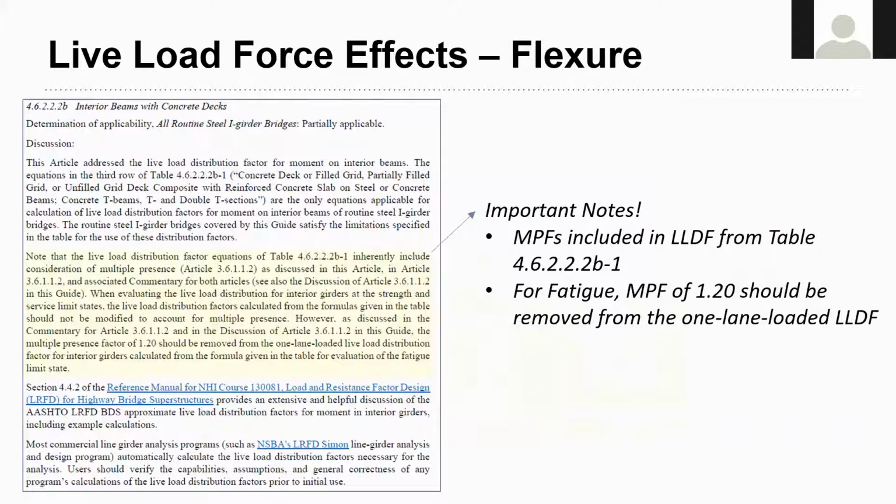What else does it say in this discussion part? Well, there's some important information, as Dominic kind of alluded to as well. Important notes: multiple presence factors, MPFs, are already included in the live load distribution factors from that table that I just showed previously in AASHTO. So I don't want to be applying additional multiple presence factors to those computations that I come up with from